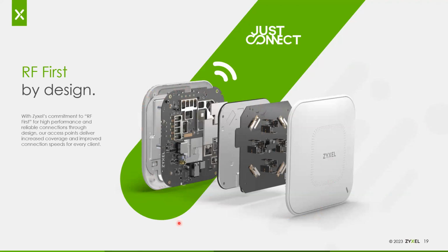So one of the things you will notice if you handle one of our access points after handling one of our competitors is our access points weigh a lot more. And there's a reason for that, and that's having to do with prolonging the life of the components here. So we're talking about a solid state component. So what causes failure? Number one cause of failure over time is heat fatigue. The little switches in the chips can actually get stuck, or you come into issues with the solder joints failing due to heat fatigue and flex.